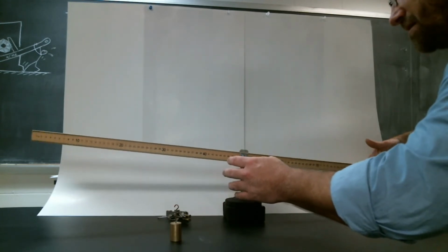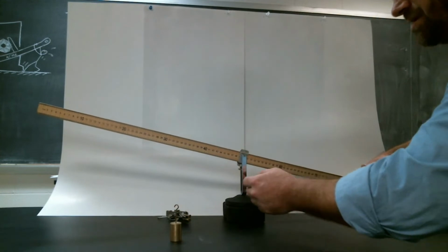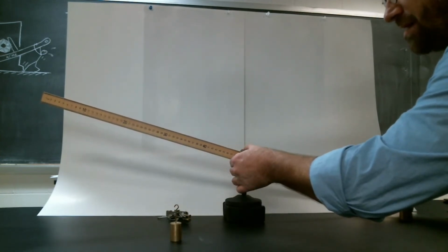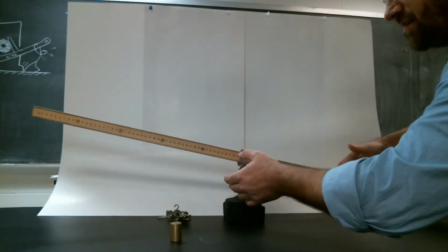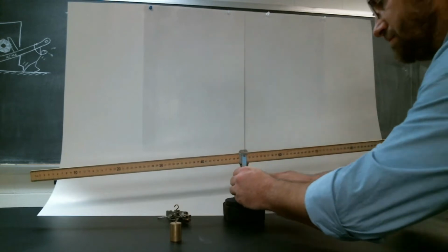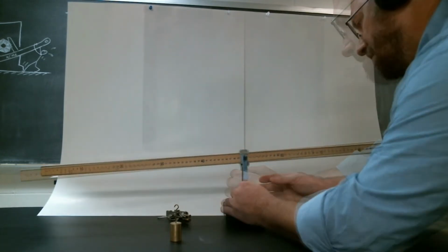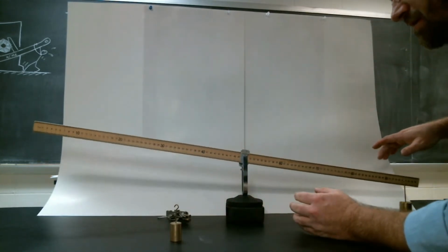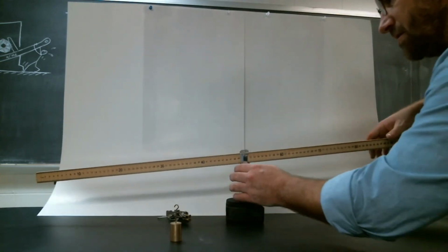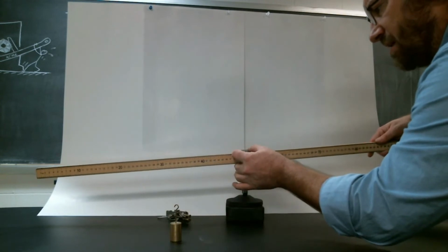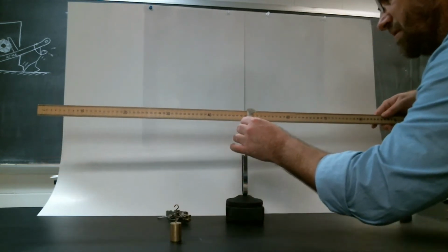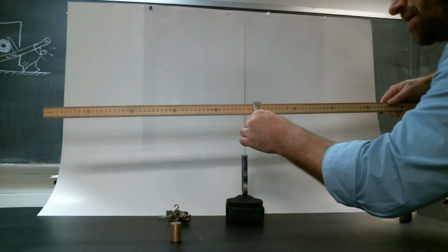Give it a little bit of a nudge. See what it does. Keeps acting the same way, so we need to put more mass over there. Keep on doing it. Don't go too fast at a time. See, it seems to be settling in on this spot, so that may be a little bit too heavy on that side. We'll bring it back this way just by 0.5 millimeter. That seems good. So we tighten it gently.